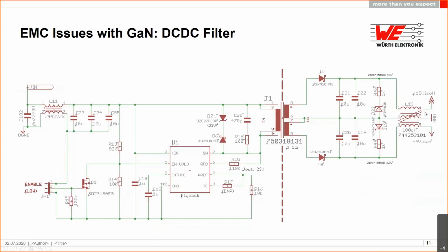This is important. It has three phases because the current must flow through the core back and forth. If you do not integrate the common connection here, you will immediately get saturation of the common mode choke. So the whole current must flow through the core. With this combination, we get good CMTI immunity together with the small interwinding capacitance of this transformer, and therefore you get lower EMI problems in the measurement.